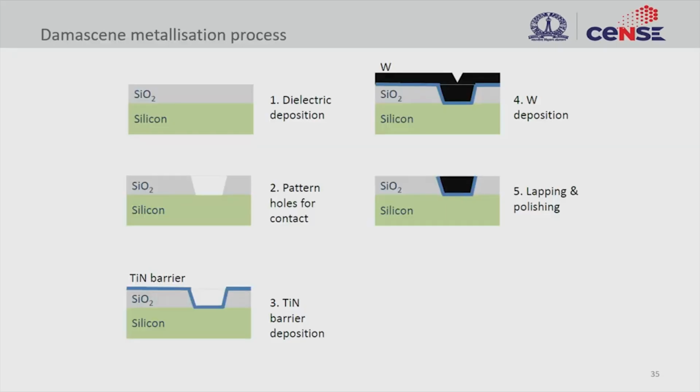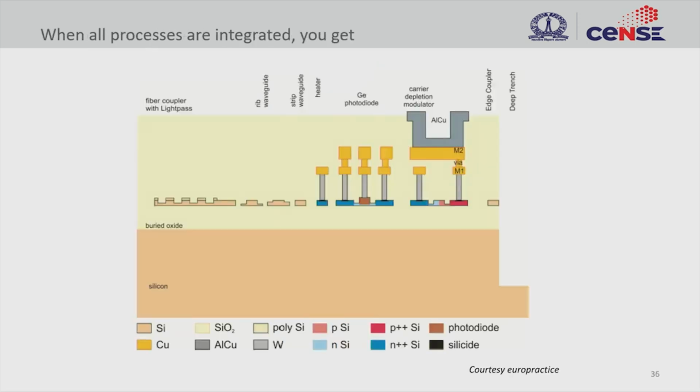So finally, metallization. Once you have this flat oxide, we will follow lithography and etching steps in order to make these trenches, and these trenches can be filled with metal deposition that we saw earlier, and then you do the CMP, right? When you repeat this process, you can build complex structures, as we saw earlier, that should result in the desired cross section that you want.